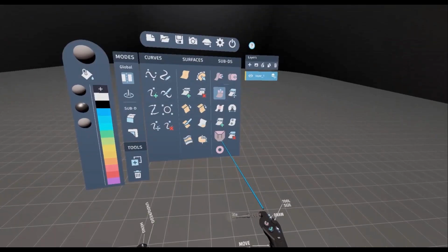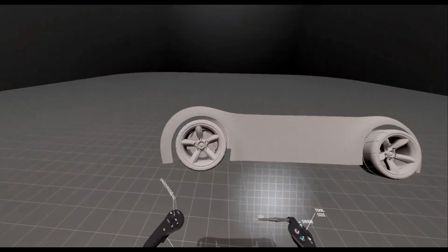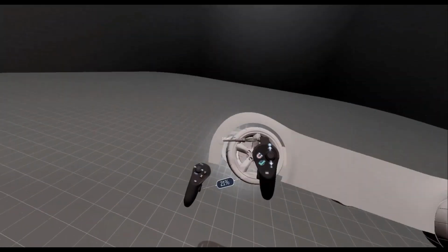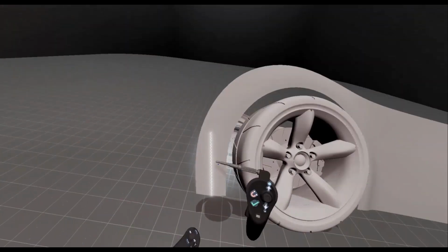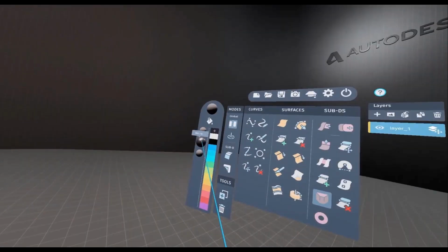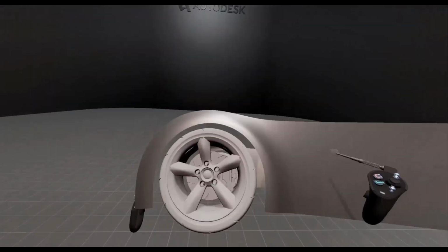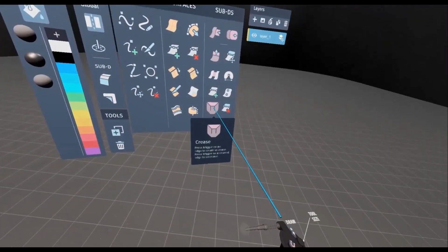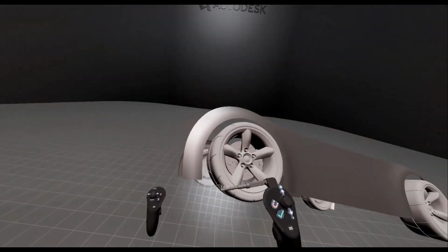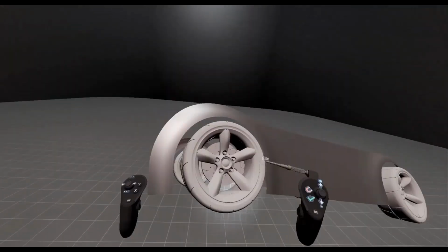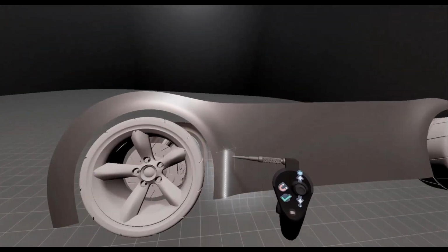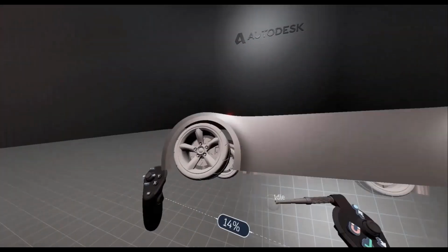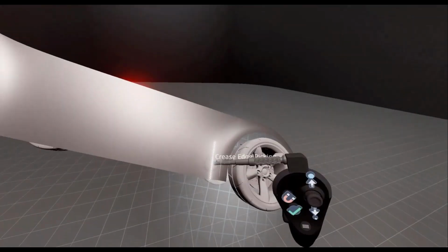So again, there was another example where they selected the one edge and then was able to use a thumb pad to select the entire edge of the model. Now we're going to do a paint select here and do some creasing, but first you're going to quickly change the material so it gets something with a little bit more shine to it, so you can see the creases a little bit better. Going back into the crease tool, going to paint select those edges, and then that's creased. And same thing on the other side.